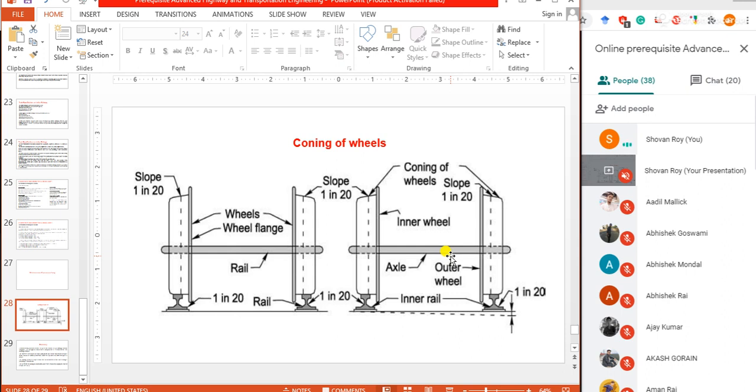Sway is the movement in the lateral direction. Due to the coning of wheels, these side movements result in the tread circumference of one wheel increasing over the other, as both the wheels have to traverse the same distance. This causes one wheel to slide.